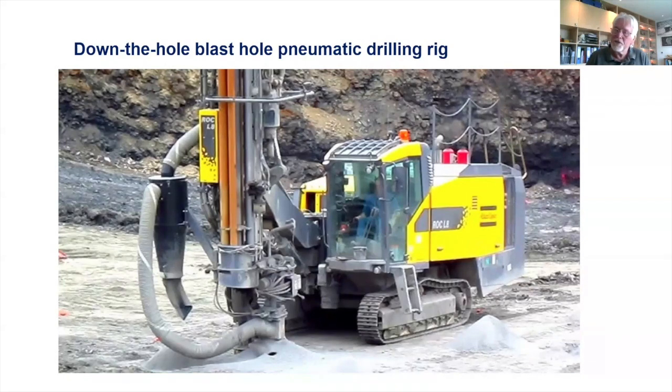A masonry drill isn't actually screwing out the material at all. It's just going bash, bash, bash, and turning very slowly. And little tungsten carbide buttons do the bashing. And then it sends dust up to the top, and on you go. If you're drilling through limestone, one of these bits will last for weeks. If you're drilling through sandstone or gritstone, it's a 50th of the life. It's drastically different. Free silica is deadly to metal.